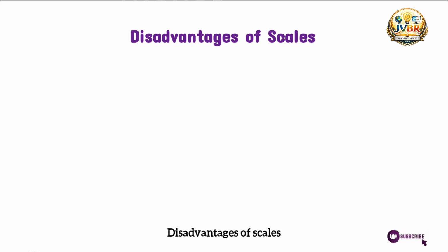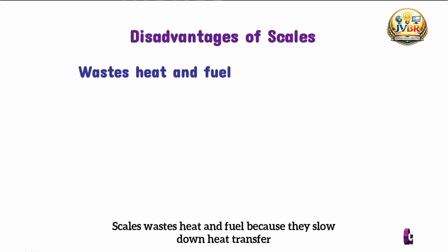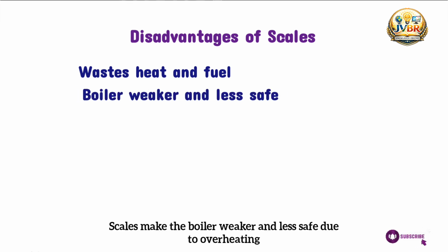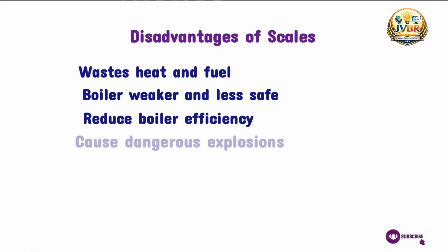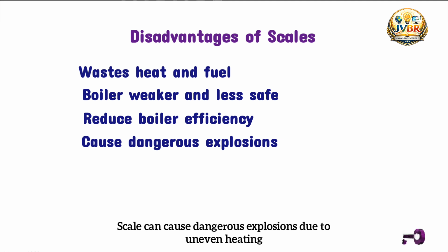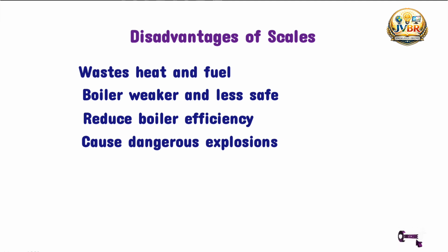Disadvantages of scales. Scales waste heat and fuel because they slow down heat transfer. Scales make the boiler weaker and less safe due to overheating. Scales reduce boiler efficiency by causing blockages. Scale can cause dangerous explosions due to uneven heating and sudden steam formation.